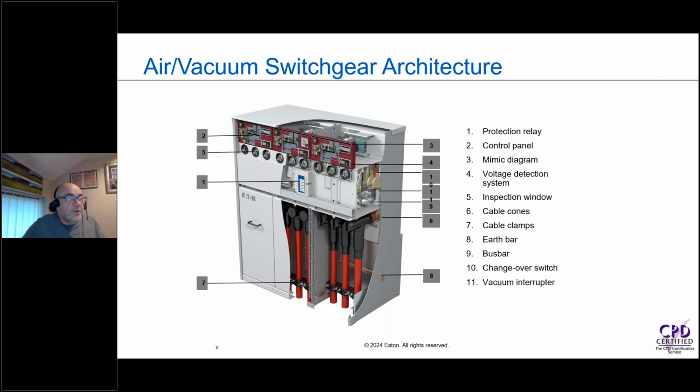If we take a little cutaway now of some SF6 free ring main unit, you can see here a cutaway that shows all the primary cables coming in from the bottom. Across the top, where you've got the wine-coloured panel, is where all the switching ports are, to bring the vacuum breaker in or out of service, and to earth the cables down. And on this particular product, note number 5 is where we've got some viewing windows where you can actually view the contact arm position, and you can also see what position the service or the disconnector switch is in as well.